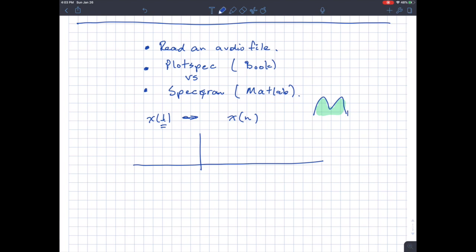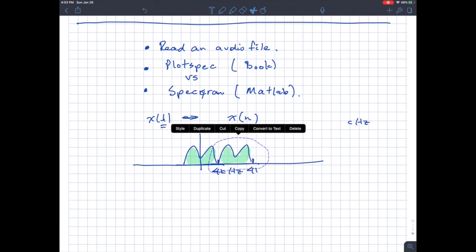okay, and we're going to be looking at speech. Speech has a bandwidth of about 4K hertz. All right, so let's pick that up. The first replica of speech would show up right here. So let me first copy that. So the zeroth replica would show up here. And then the next replica would be up at 8 kilohertz, okay, centered at 8 kilohertz, because the sampling rate that we're using in this example is 8 kilosamples per second.